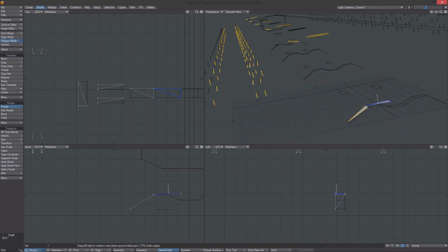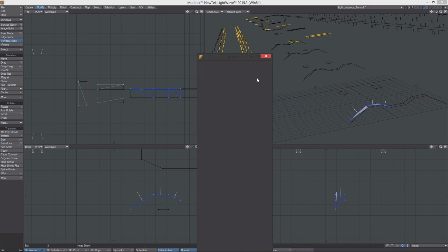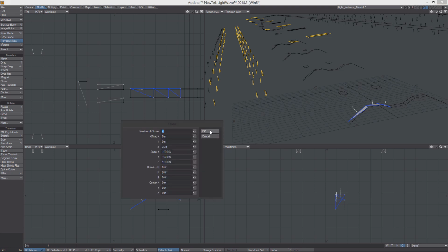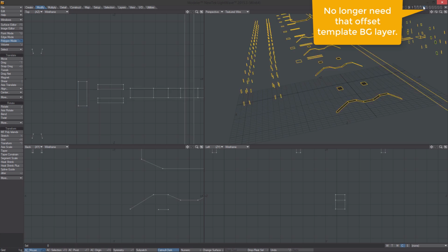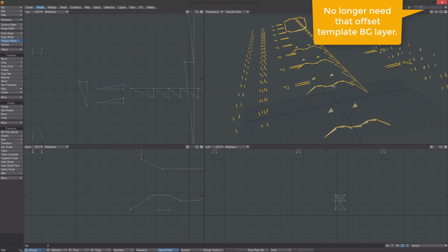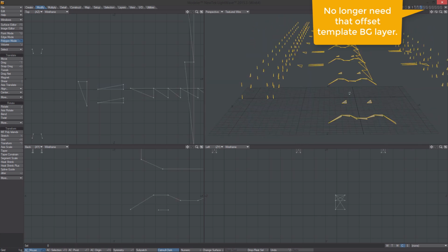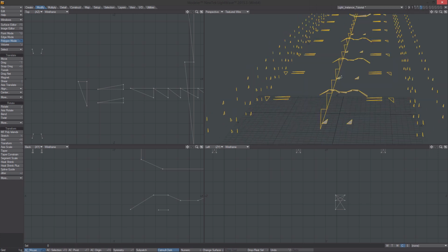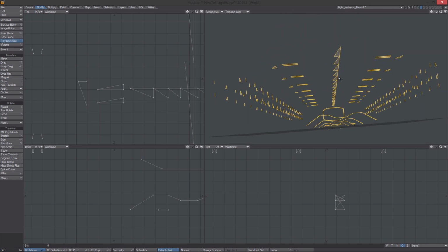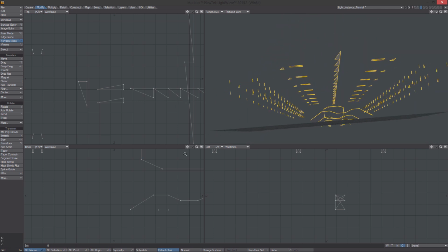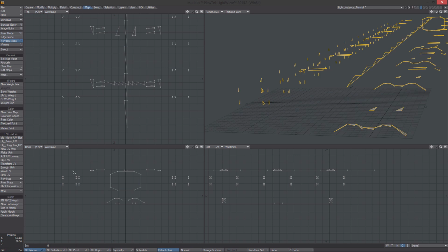Now I'm doing this center thing. Same thing, heat shrink. And that's all I'm going to show you, but you get the idea, and then you can just clone it. I think it took me like 6 minutes to do this one here. And you'll notice for that top long light, I broke that one up into 7.5 meter sections because of the aspect ratio. You don't want the sampling to get bad if you were to leave that as one triangle with that huge aspect ratio.